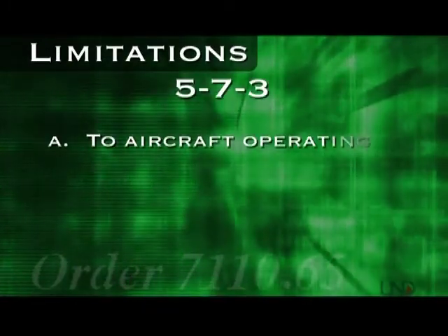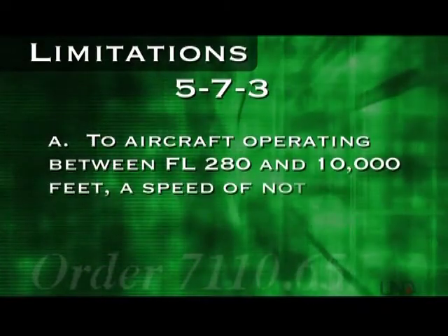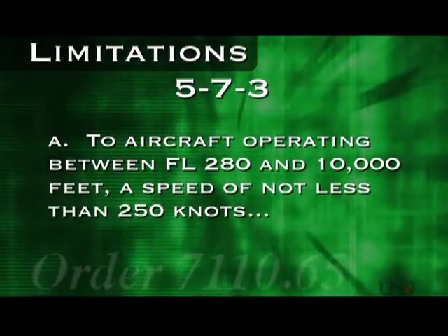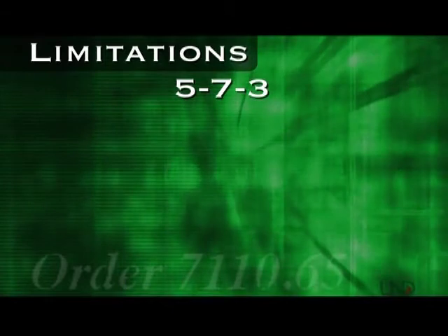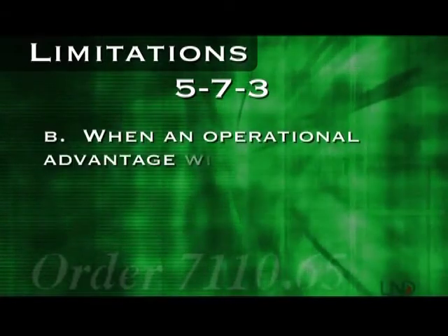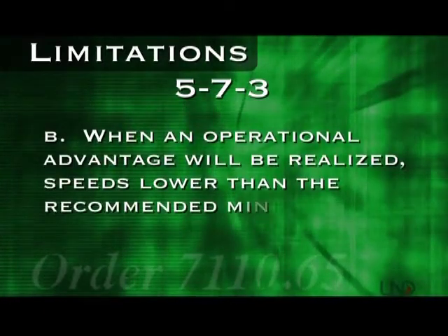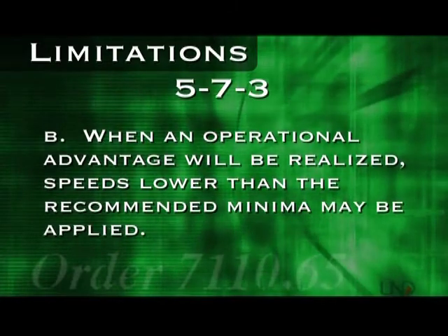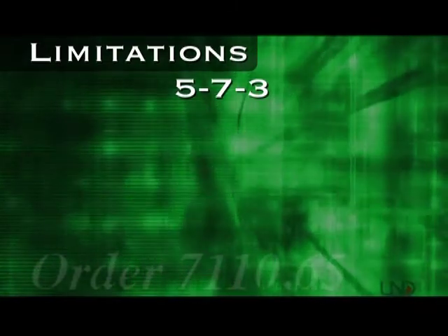To aircraft operating between flight level 280 and 10,000 feet, a speed not less than 250 knots. However, when an operational advantage will be realized, speeds lower than the recommended minima may be applied. Now for what concerns us the most.